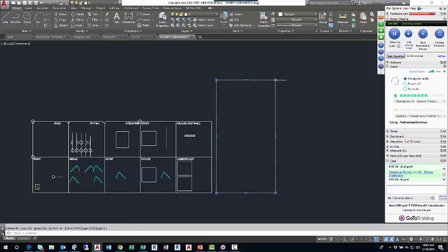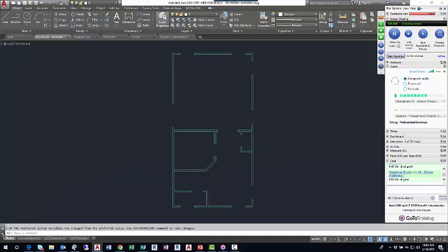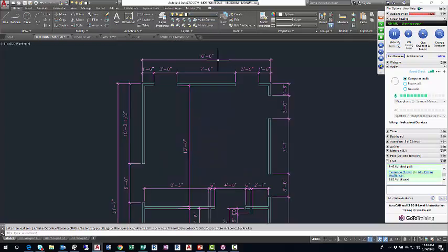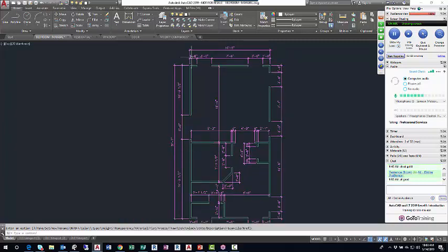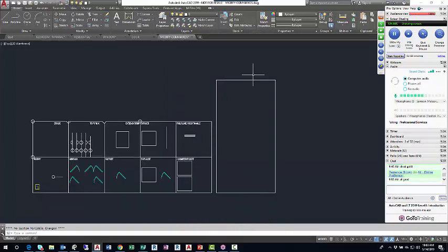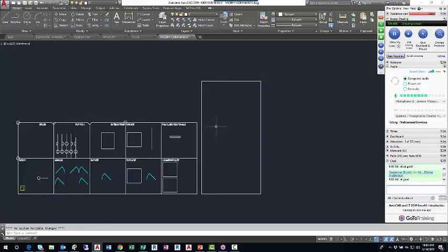So that's not a modify command, that's a draw command, right? Now that I've used my draw command to create the start point for my floor plan, the dimensions that I have turned off here, turn them back on with the little on tool. The initial dimensions are outside dimensions. This 16.6 is the outside face. This 31.7 is the outside face of the floor plan. I'm going to use an offset command. All my walls in this example, it's a practice drawing. It's not a real plan.